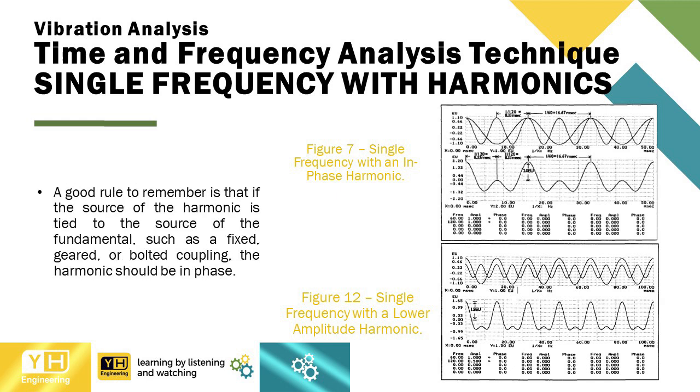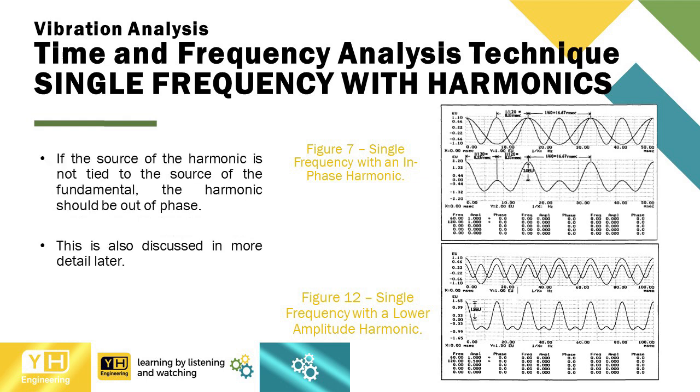A good rule to remember is that if the source of the harmonic is tied to the source of the fundamental, such as a fixed, geared, or bolted coupling, the harmonic should be in phase. If the source of the harmonic is not tied to the source of the fundamental, the harmonic should be out of phase. This is also discussed in more detail later.